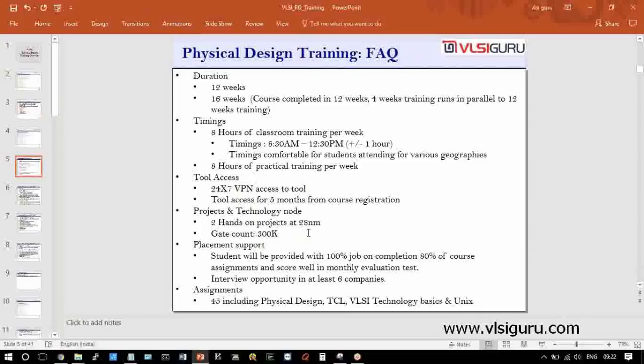Now, why do we need a separate tool for timing sign off? Because, as I told you, every physical design engineer, at the end of the day, will be struggling to meet the frequency. For us to meet the frequency, somebody has to sign off. They have to tick and say, yes, my design will work at this frequency after it comes back from the manufacturing fabrication house in Taiwan or wherever it is. That is why we need a separate STA tool.